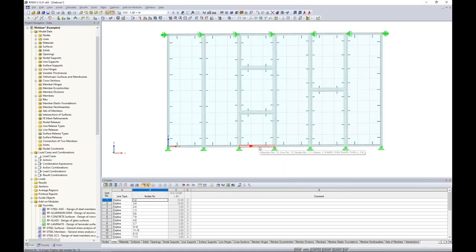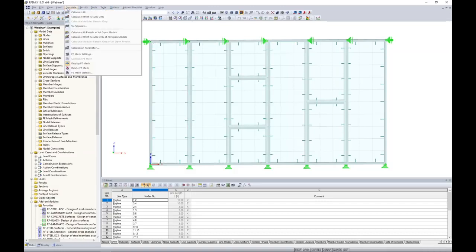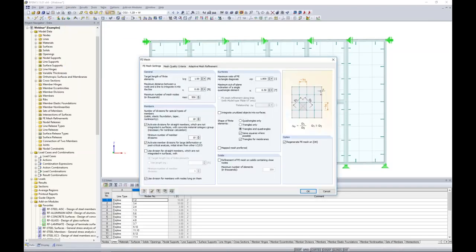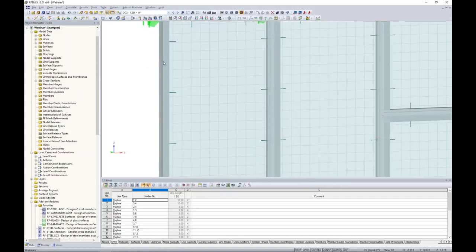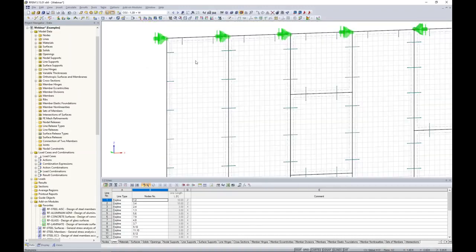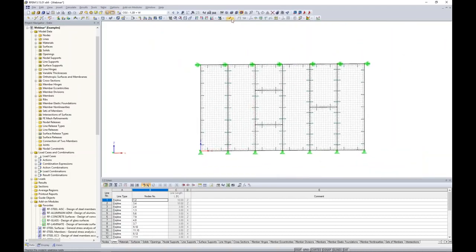And I can see here that my FE mesh is a little bit too large. I only have 3 FE mesh points along the width of these glass panels. This really just isn't ideal to give us accurate results. So it's always suggested that we need to go smaller than this. Now this will increase our solution time slightly, but in turn, of course, we need to see accurate results. So under Calculate FE mesh settings, let's try something like 0.25 feet, and we can regenerate this again. Well, this looks much better, and I know that's a little difficult to see, but maybe we turn this into wireframe view. We can see the FE mesh settings along the width is much smaller, so that looks much better.